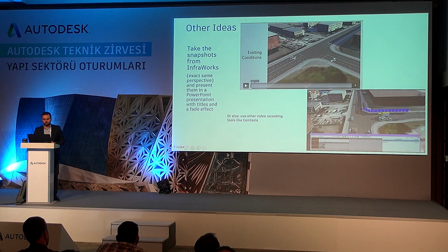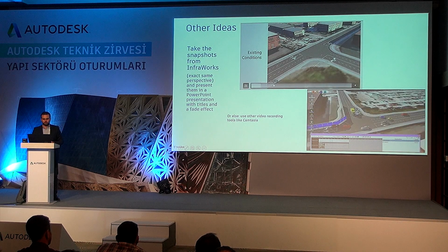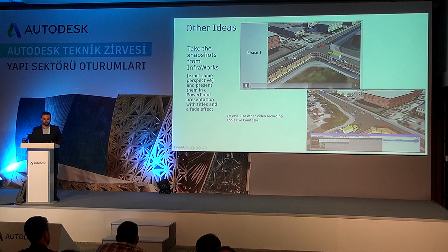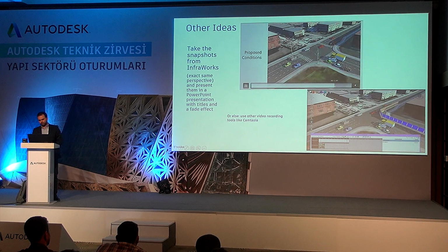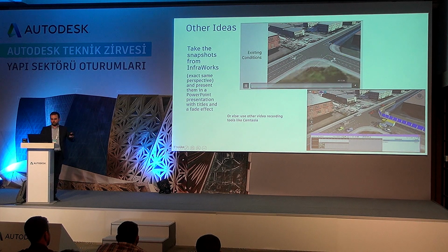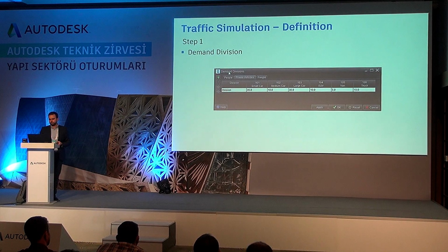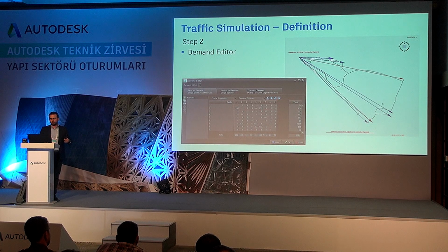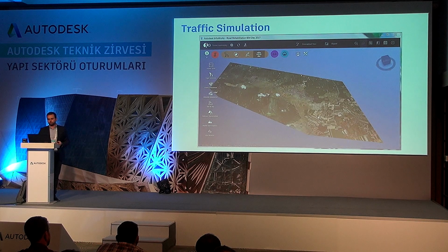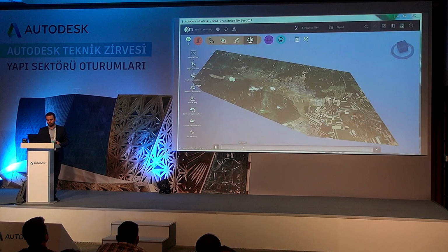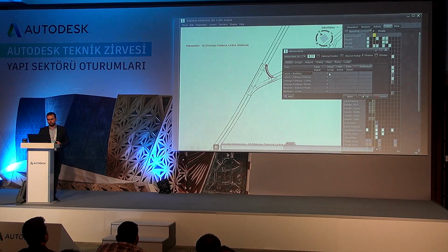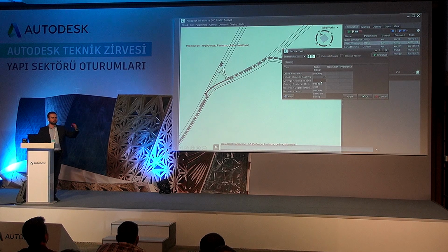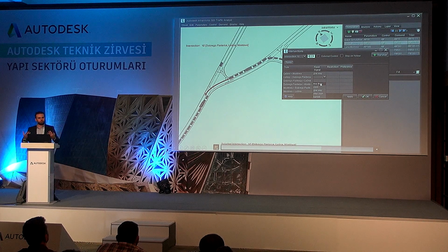Then you can generate different scenarios. This is how things are. This is when we close one lane for rehabilitation, we close the other lane, and then generate analysis and tables and views. Traffic simulation is based on data. So you input the data in, which you currently get from the municipality or the governmental authority. You specify constraints. And again, you will see these animations in 3D. This is just the traffic analyst panel where all of the traffic simulation parameters go in.